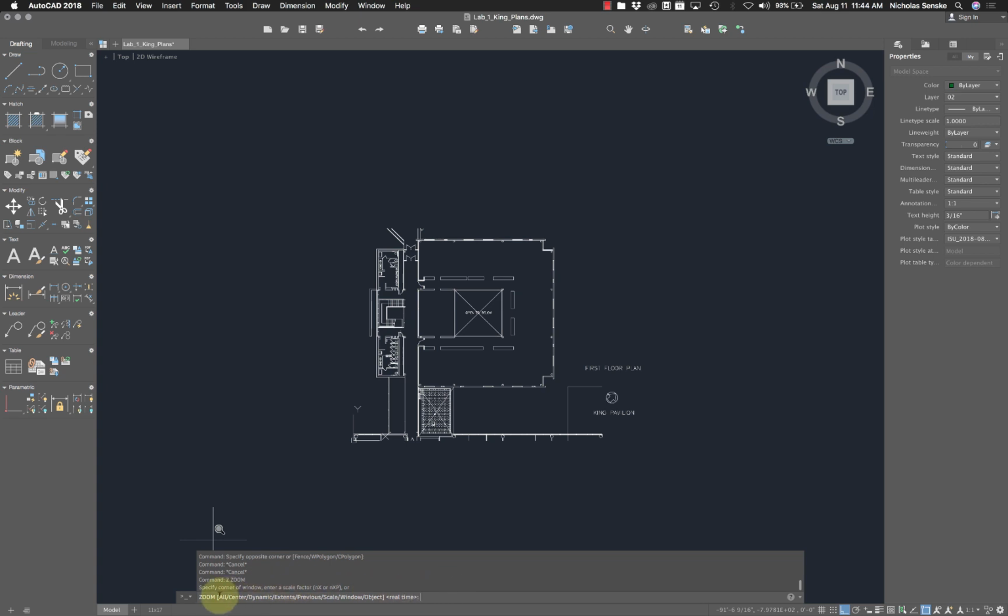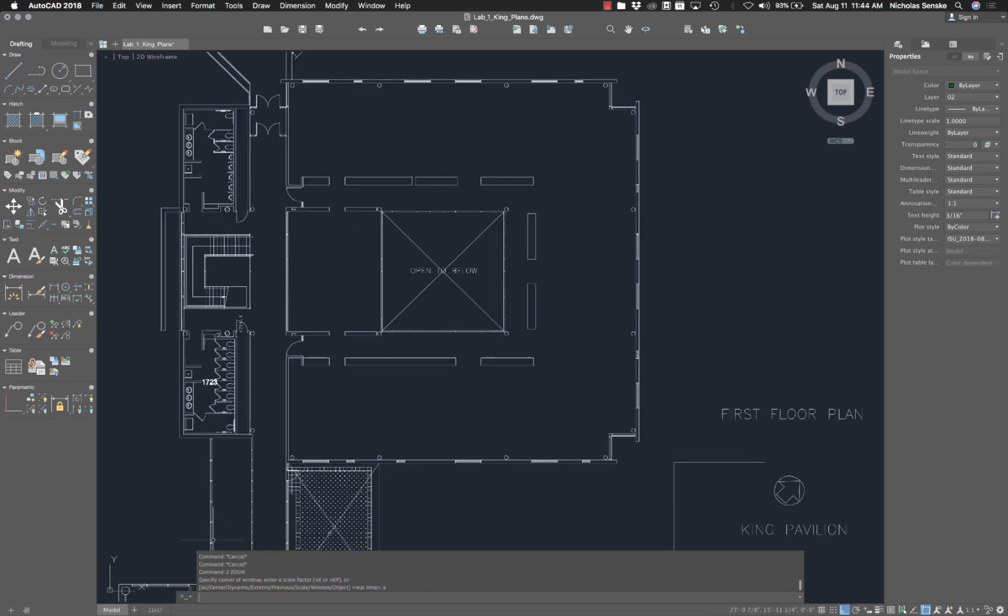You can zoom everything by saying A for all. So just type in A. Usually you just have to type the first letter of each command. And as you get to work with AutoCAD, you'll get more and more used to it. So that's again Z, A, real quick.